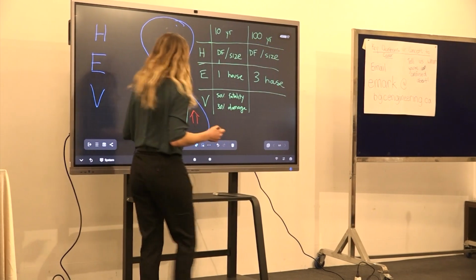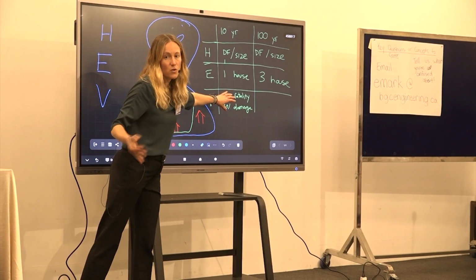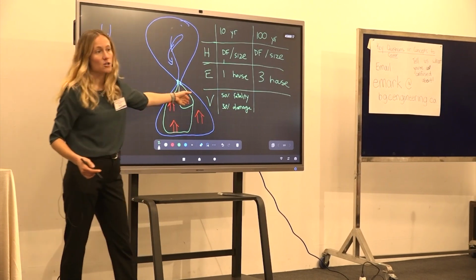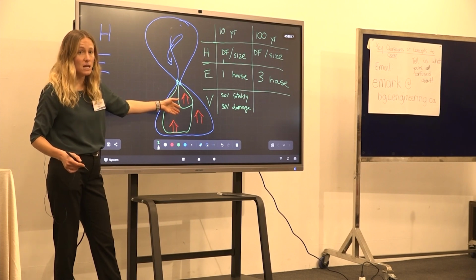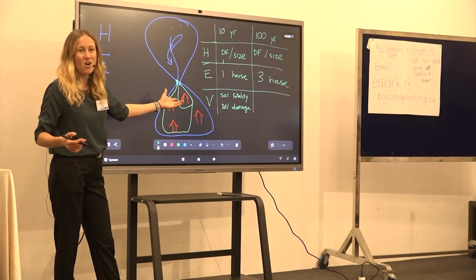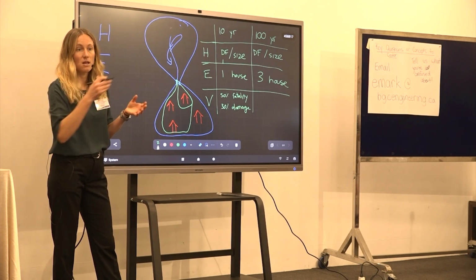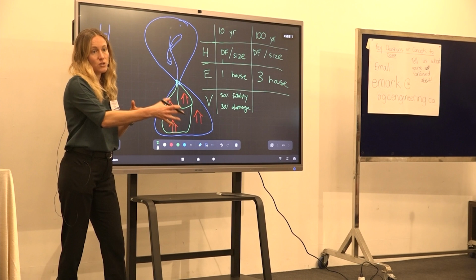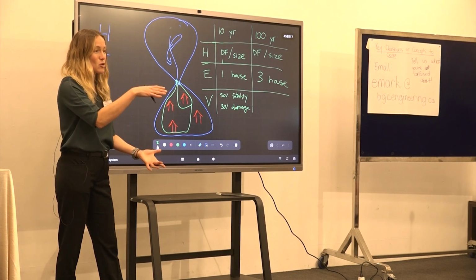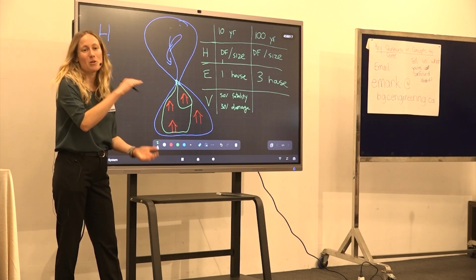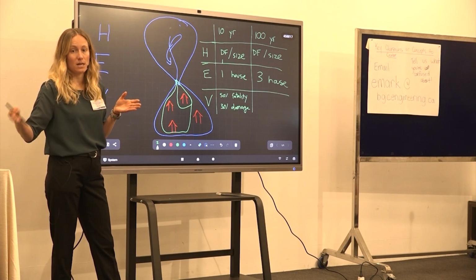And then the vulnerability, right now I'm kind of making up numbers for an example. How you would actually determine vulnerability is something called a fragility curve. And that relates the hazard, the hazard intensity, sorry, that's the word I'm going for, the flow depth and the flow velocity to how much damage you would expect.